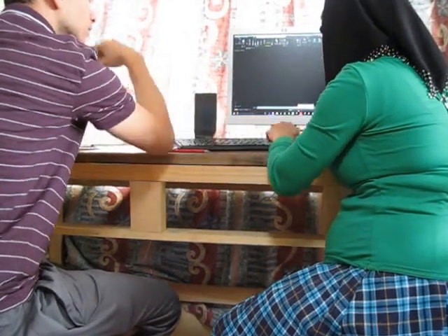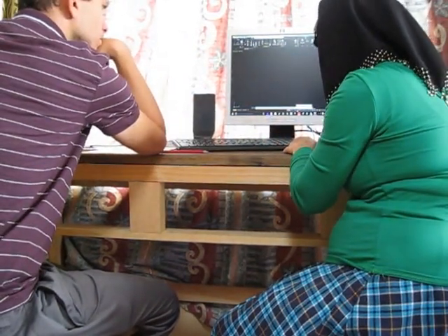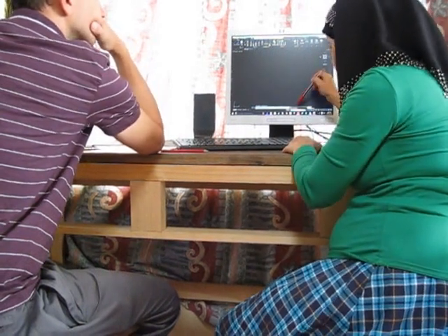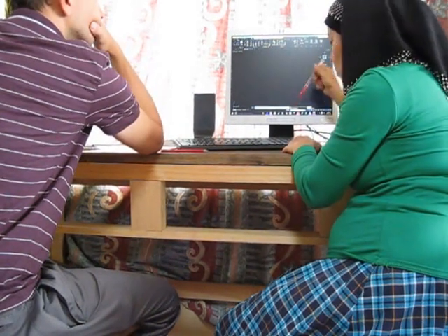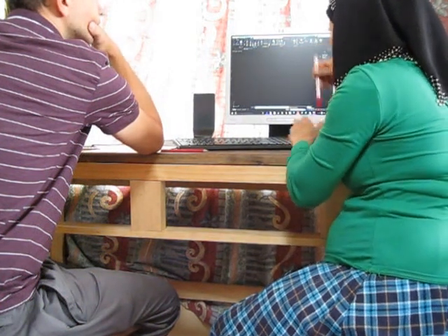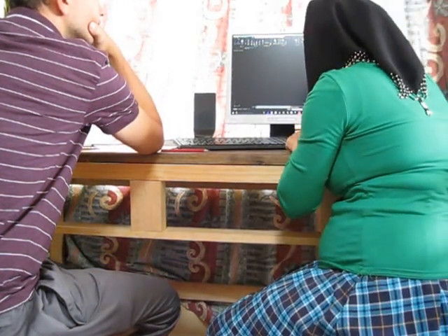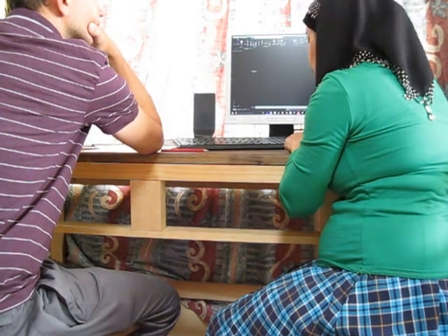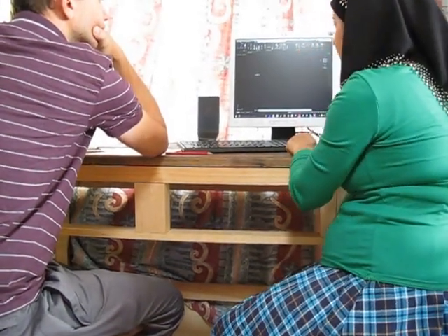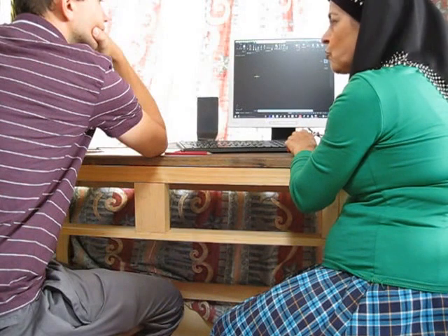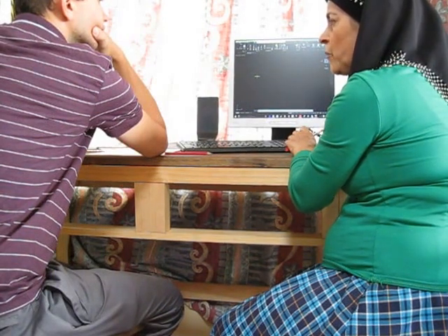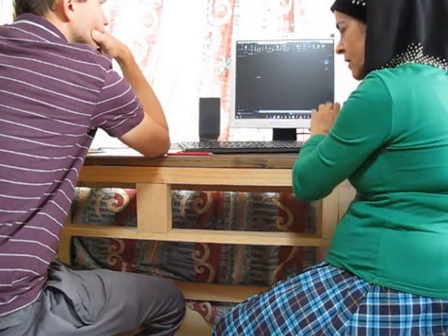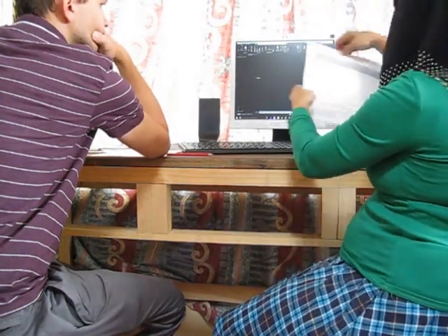No, it's better not to use it. I just prefer the mouse. When you click on this, the icon that used to be gray turns to blue. So blue means it is on. Therefore, you are right now in ortho mode, so all the lines that the mouse is drawing are going to be vertical and horizontal. Okay, so you know this.